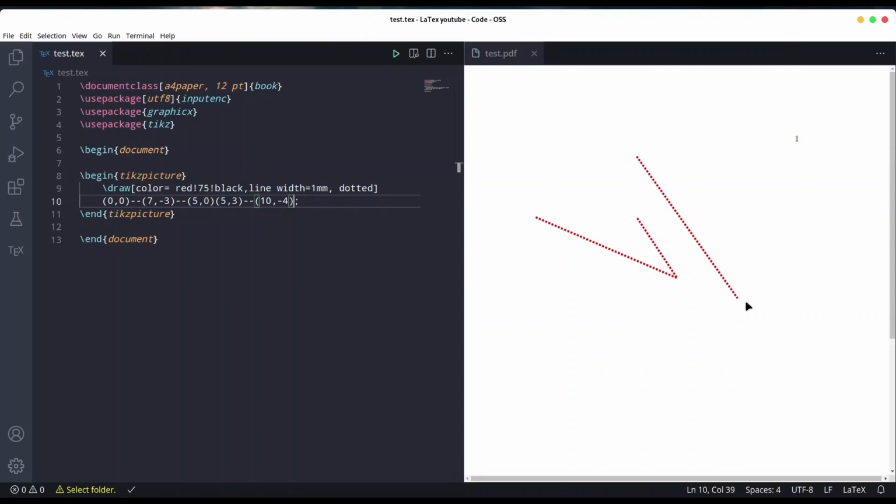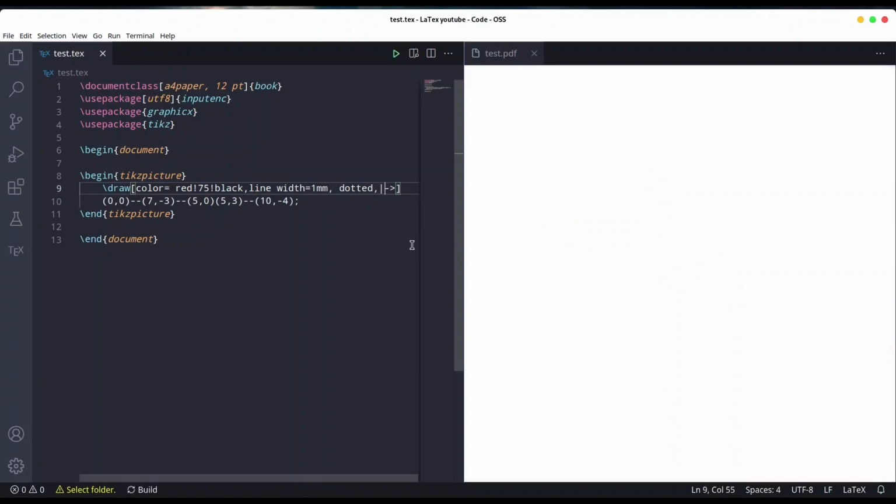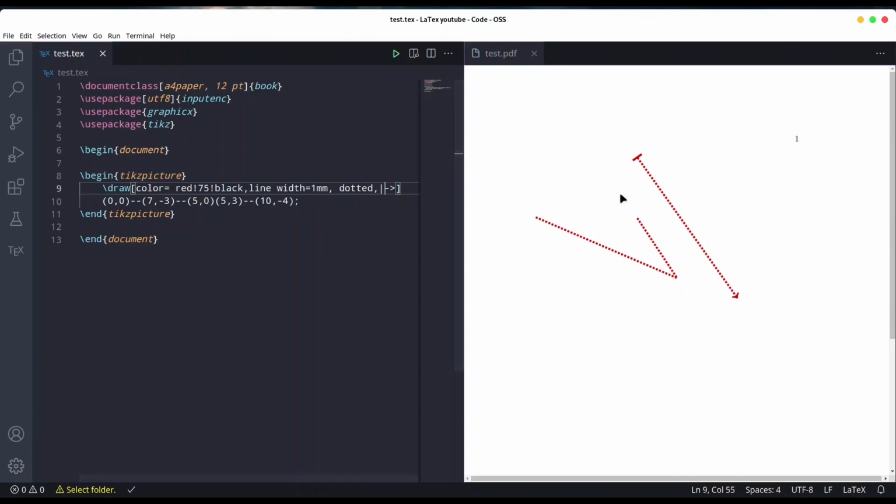This is our result. But now, what is going to happen if I want this ending arrow, like this? And let's say with a vertical line in the beginning. Save it. You see, we are going to get that result, but only with the second part of our line. So if you want to have both starting and ending points, you will have to provide two drawing commands.